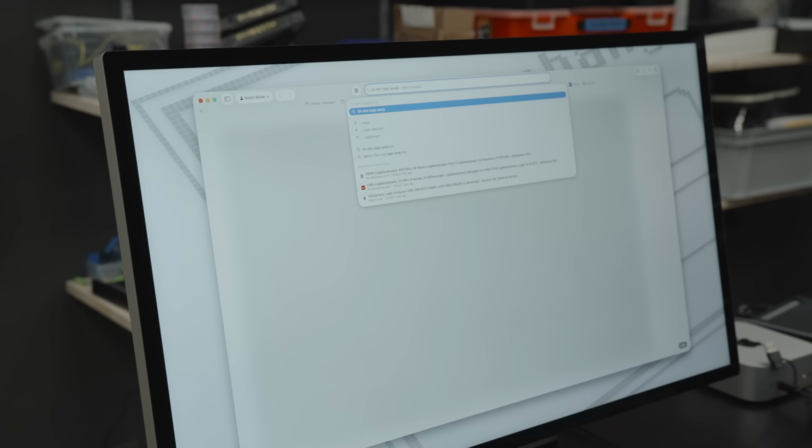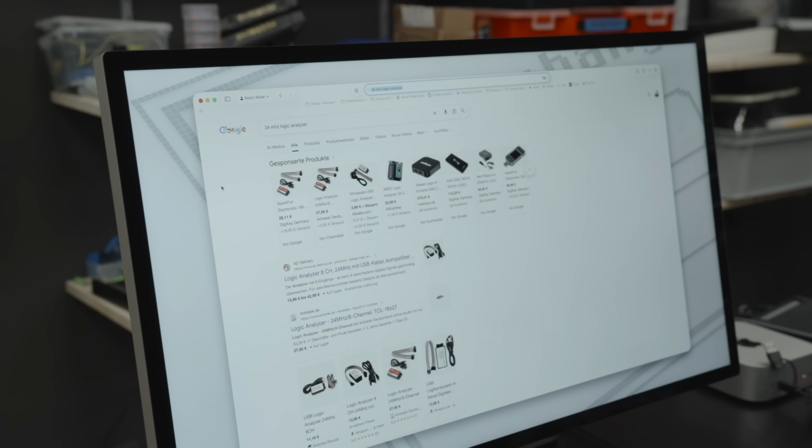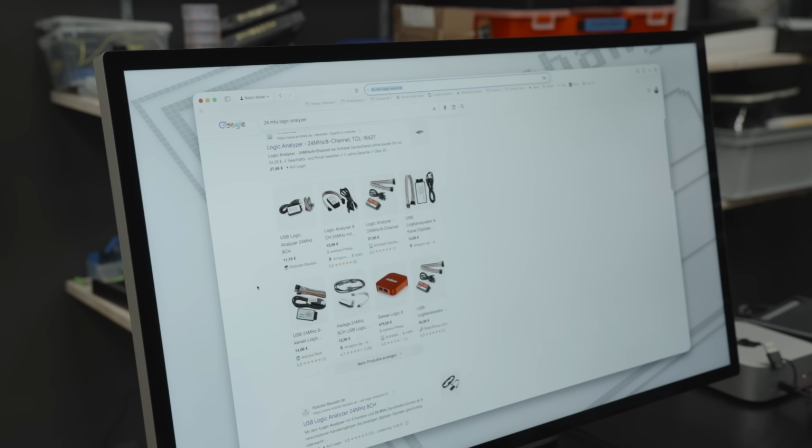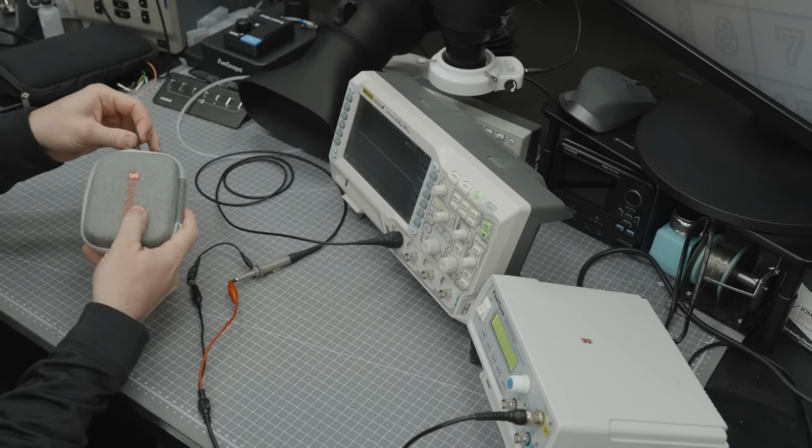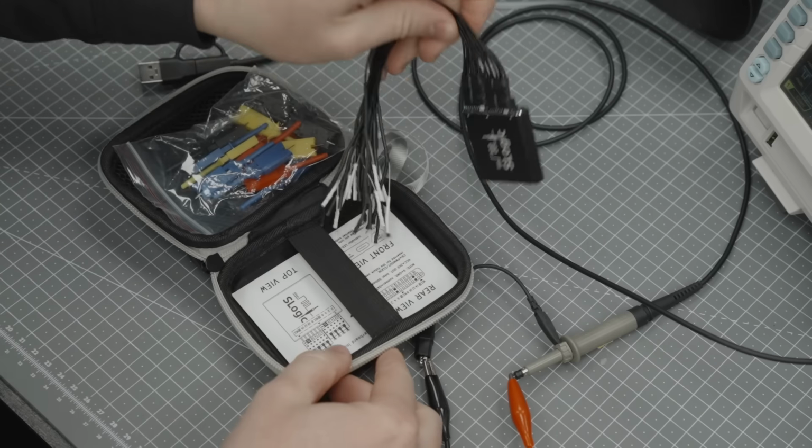So giving those $5 24 MHz logic analyzers a quick look reveals that we're pretty much already leaving their comfort zone. I still think those are amazing if you are tinkering around with UART or other buses with a low baud rate, but anything above that is pretty much impossible. Let's hook up our S16U3.